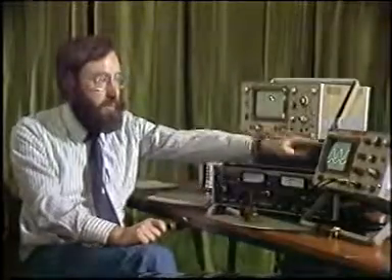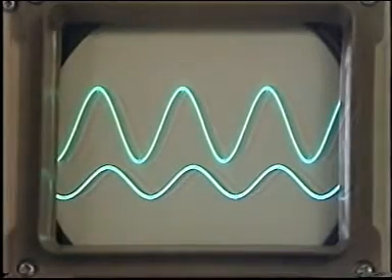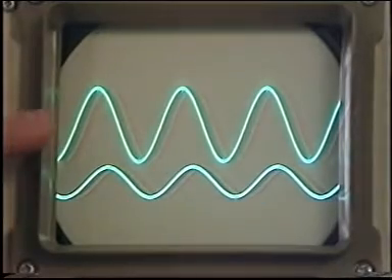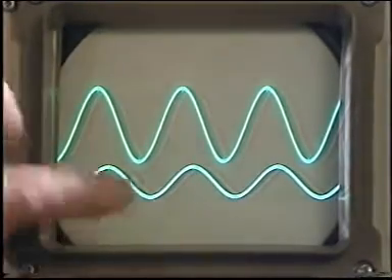As a result, when we come to do calculations on the signals and on the networks themselves, all we need concern ourselves with is the frequency, the amplitude, and the relative phase. I say relative phase because the phase angle of a given signal is always measured with respect to a reference sine wave somewhere in the circuit, normally at the input.